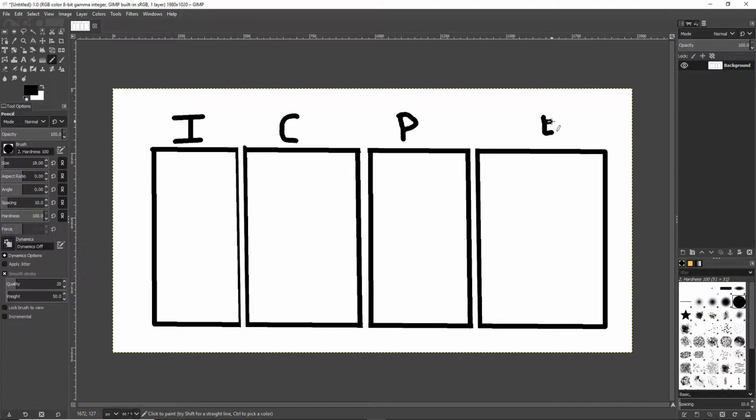So, what we're going to do is draw the piston. The piston is at the bottom, and it comes up, and then it goes down, and it comes up. Every time it travels a distance from the bottom to the top, that's called a stroke. That's why we call this the 4 strokes. So I'm not going to draw a piston, I'm going to draw an arrow. And the arrow will indicate whether the piston was going from the bottom to the top or from the top to the bottom. So in the intake stroke, I need to pull air and fuel into the cylinder. And the way that I do that is I make the piston travel down and it creates a vacuum, and that vacuum pulls air and fuel into the cylinder.